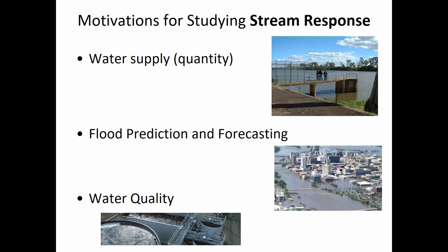and then those soil particles become suspended in the water, and you can almost taste it in the water that we get from the tap here. Maybe it's just my mind playing tricks on me, but I seem to think that the taste of the water changes when the source is brown because they're having to add more coagulants. Here in Huntington, they have the ability to add powdered carbon to the water, because when there's a lot of heavy rains, it's going to take the pesticides and the fertilizers that farmers use in agricultural areas. And so when there's a lot of peak flooding into the river, it decreases the water quality, and they have to kind of change their treatment that they're using here.